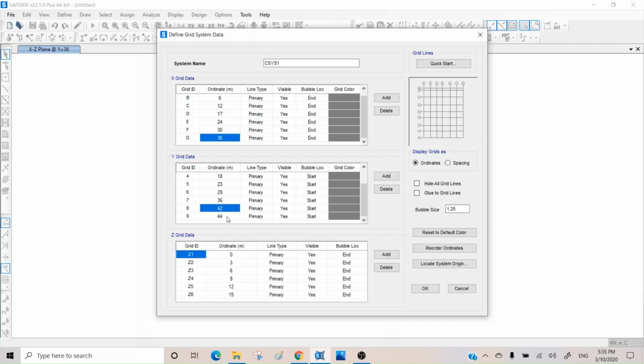For example, I don't want to have 9 bays here, so I can come here and delete this one and just adjust it again, like for Z. If you want to change it again, you need to do it here. So for example, you can change the story height a little bit. First to a story height of 4 meters, and then, this is incremental, so that would be 8, and here 3 meters, 11 and 14 and 17. So I'm changing my story height.